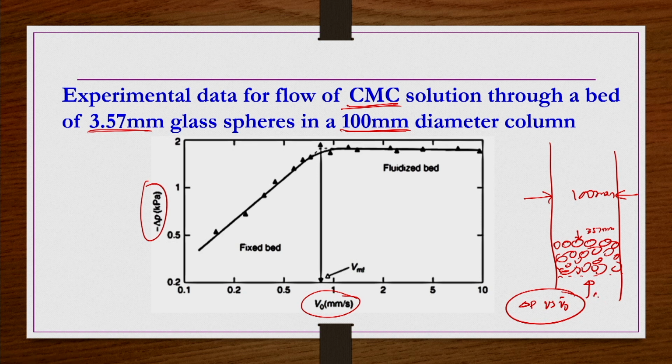That was captured experimentally, they have calculated it and put it in pictorially like this. Now we can see these points are experimental points, actually all of these are experimental points. So they are slightly scattered, but if you draw a curve fitting line, up to a certain velocity it is gradually increasing, and then there is a diminishing of slope, and the pressure drop slightly increases up to point C, and then after this the pressure drop remains almost constant.